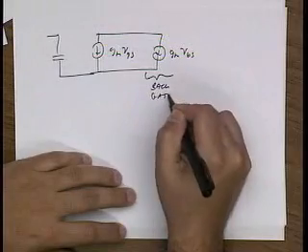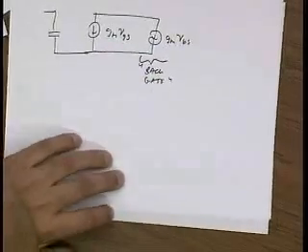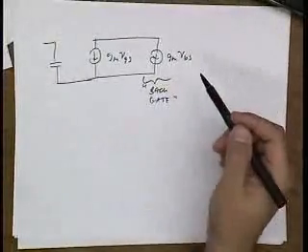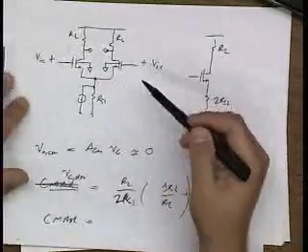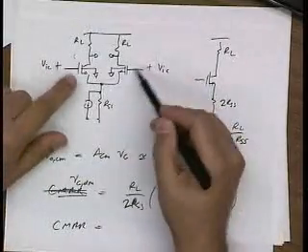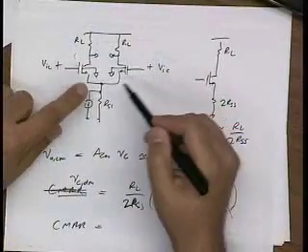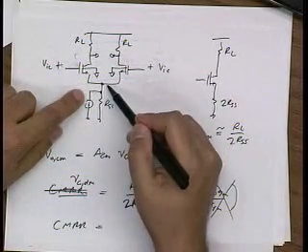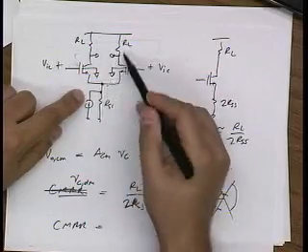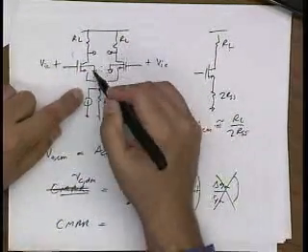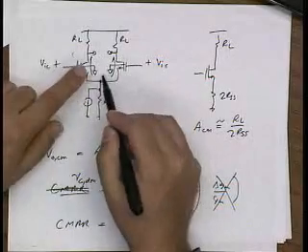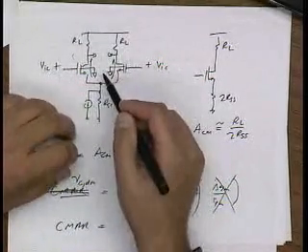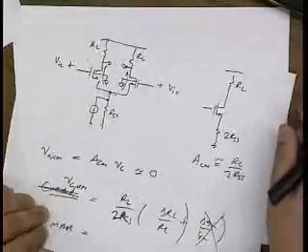It's easy to forget this back gate, but it's always there. Usually it doesn't matter, but here all of a sudden, because the source voltage is getting so large. For a common mode signal, this is just a follower, so whatever voltage I have here, I have here. If I apply a very large common mode signal, it appears at the source, and that will generate two extra current components. If these two current components are mismatched, then you end up getting a differential output signal, even if everything else is matched. Okay?